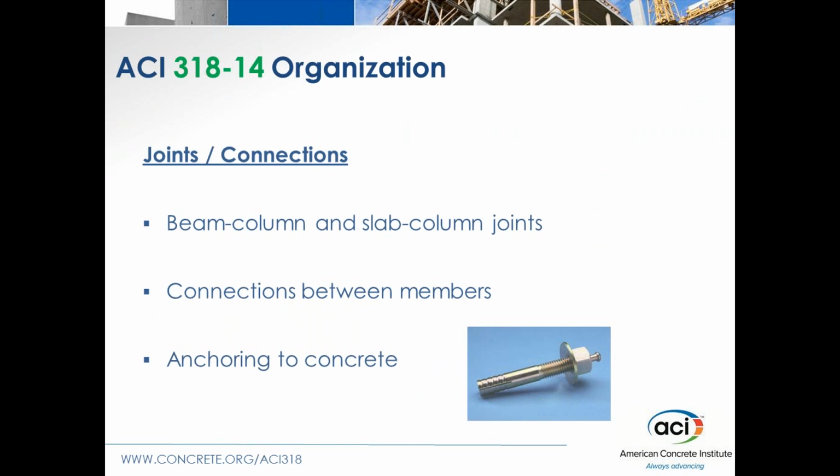And then the other one, anchoring to concrete. You will be happy to know that Appendix D, which was for post-installed anchors, which has changed probably every code cycle since they've ever been introduced in a great way, has largely been left untouched. That has been the most anchors. Unfortunately, you get the least amount of money designing them, and you have to spend the most time designing them. We still are stuck with that, but we have moved it from the appendix into a chapter of the code, so I am going to tell you that.